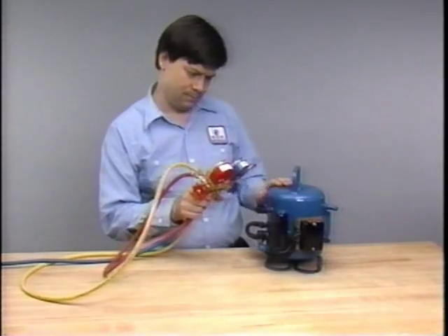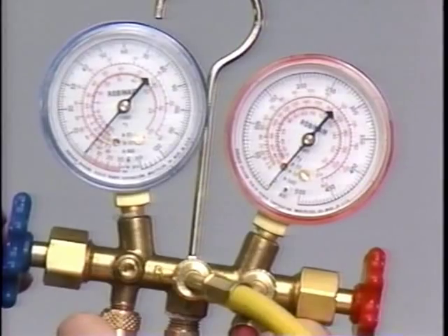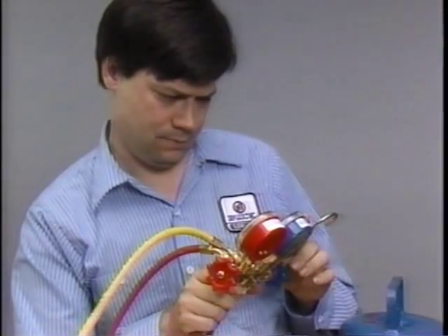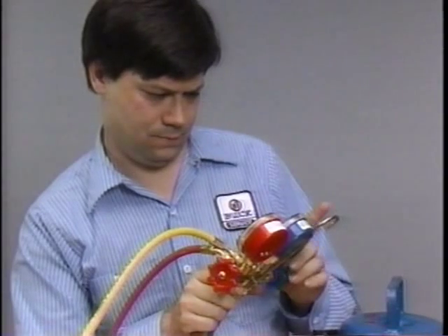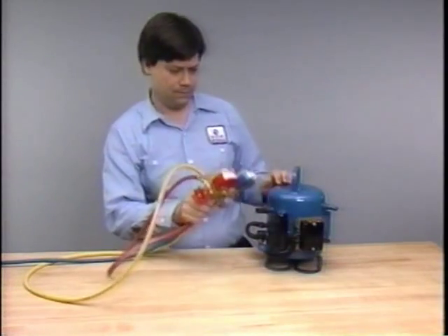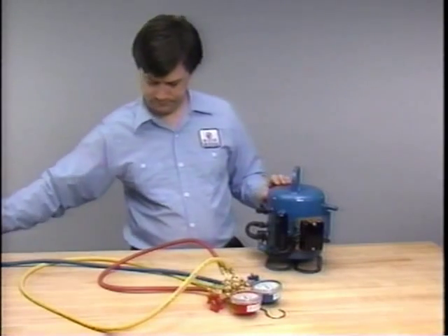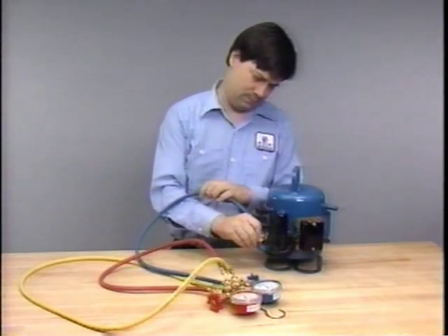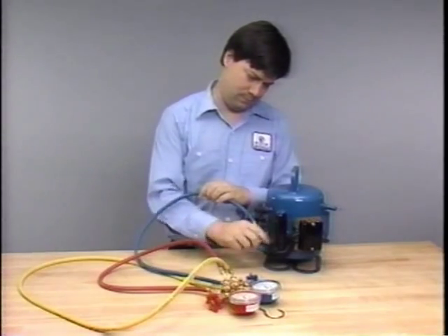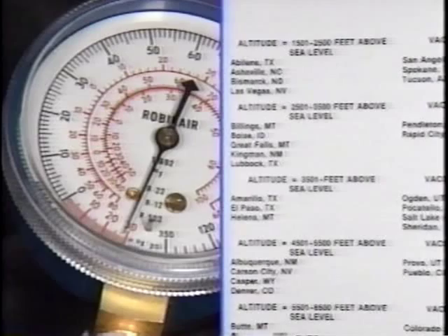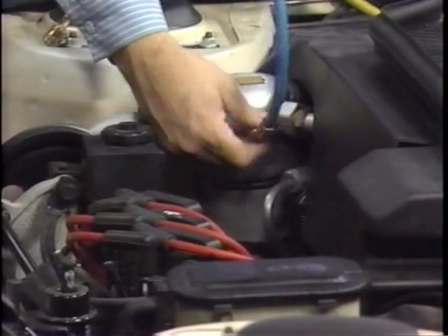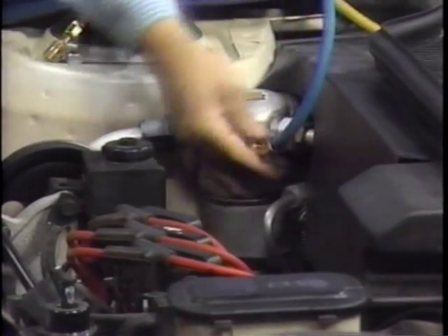First, check the low pressure gauge and vacuum pump. The gauge should read 0 when disconnected from the system. If it does not, tap it lightly to make sure the needle is not just sticking. If necessary, adjust the gauge according to the manufacturer's instructions. Once the gauge is properly calibrated, check the vacuum pump by connecting it to the gauge and running it. It should be able to generate the specified minimum vacuum for your local altitude as indicated by the chart in your reference manual. If it doesn't, check the pump system for leaks or mechanical problems as described in the pump instructions. Hook the low pressure gauge to the low side service fitting on the accumulator.